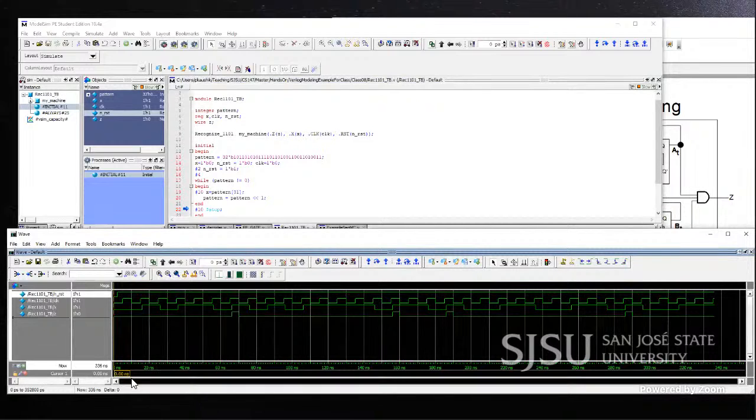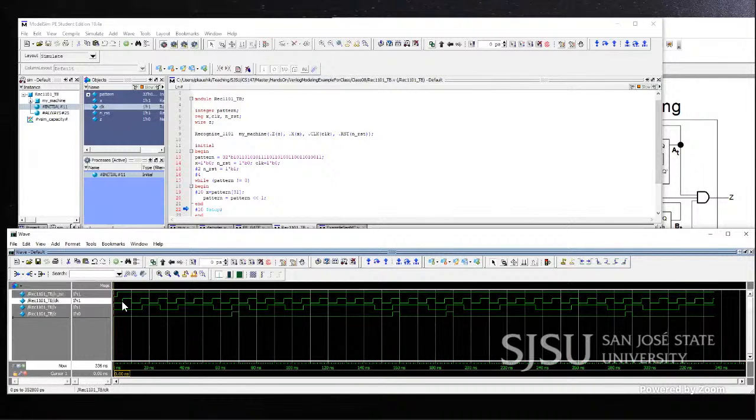So pretty much we have a clock coming out, toggling each 5 nanoseconds, and then we have some bit pattern incoming. If you see, we have possibly recognized 1101 successfully in this machine. Let's say it becomes 1 here, 1 here, 0 there. Is it 1, 1, 0, and 1? Okay, and as soon as it goes to 1, your recognizer output actually goes high, right?